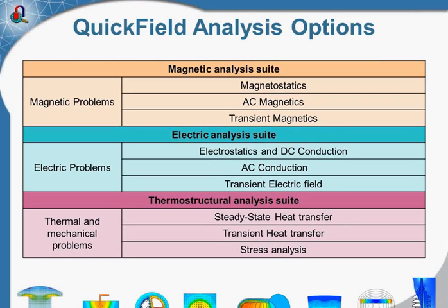In some cases, static simulations may give you enough information to improve the design, especially if you need to find proper shape of your electrodes. And AC models may be convenient for fast evaluation of electromagnetic processes, even if your pulse shape is not purely sinusoidal.